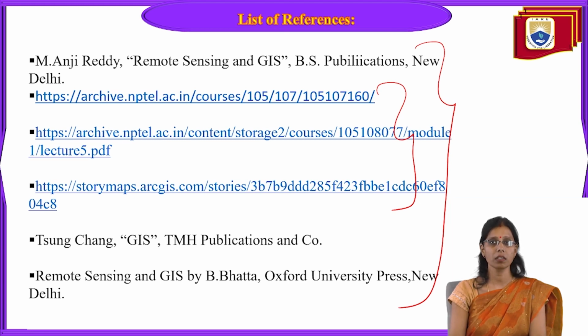So just see now, in simple terms, processing means before using a captured image, like with a normal camera also, if we capture a photo, what we generally do is increase some brightness, increase some contrast, and sharpen the image. So all that rectification we do before we use the image. This is how we do it with satellite images also. Once we use satellite images, all these rectifications should be done before we use the data, satellite data or aerial photo, right?